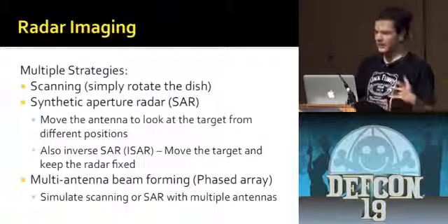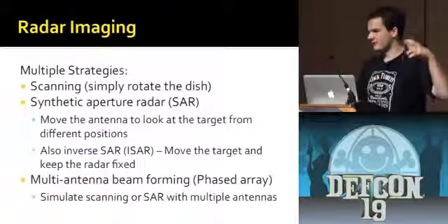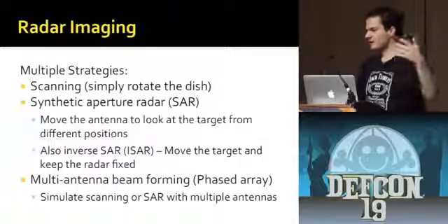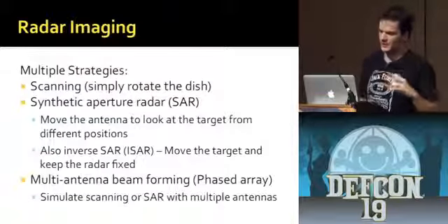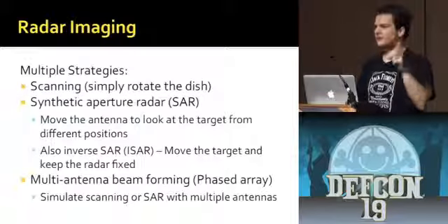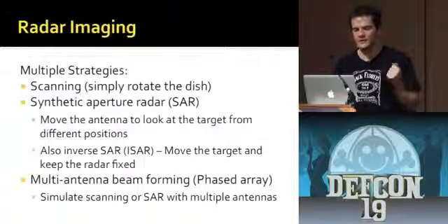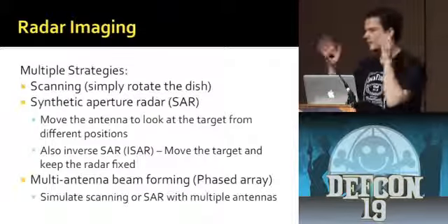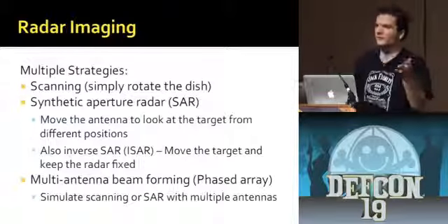There's something called synthetic aperture radar, which basically means you can get better resolution if you have a bigger dish. But the problem is the bigger dishes are more directional, so that's the advantage. With synthetic aperture radar, you're actually taking coherent measurements of the signal at different places, and you're trying to simulate having a larger dish. The reason you would do that is so that you can get a finer resolution of space. If you just point it in one direction, the beam widths on these things are like 40 degrees or something, so you couldn't see anything out there.